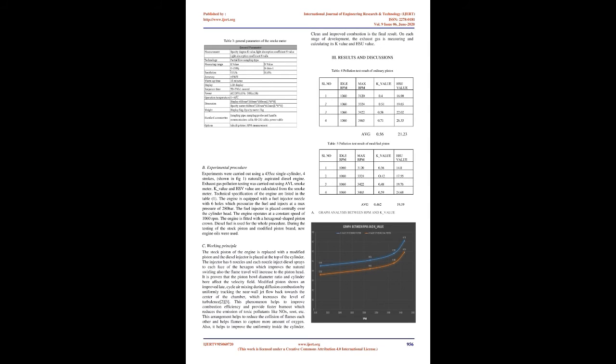C. Working principle. The stock piston of the engine is replaced with a modified piston and the diesel injector is placed at the top of the cylinder. The injector has 6 nozzles and each nozzle injects diesel sprays to each face of the hexagon, which improves the natural swirling. Also the flame travel will increase to the piston head.